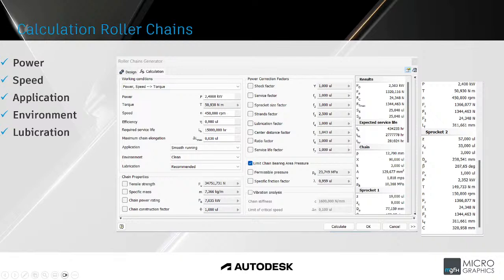So in this instance, I selected the power speed to torque, and the power I made was 2.5 kilowatts. The speed I made 450 RPM. The efficiency I left as is. The required service life, I chose 15,000 hours. The application I made smooth. Environment, I made a clean environment. And lubrication I made recommended.